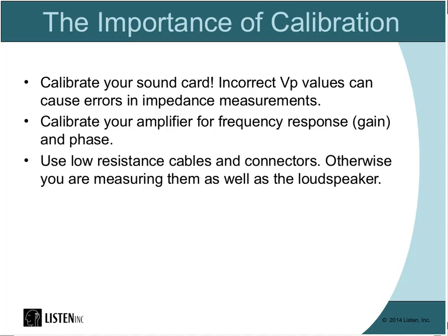And as always, it's very important to use good cables. We want to use low resistance cables and good connections. Otherwise, you end up measuring the loudspeaker and the cables together. And I've seen many cases where people got thin cable running for a very long distance, say into a test chamber, and then the test equipment's on the outside, and it can be even a couple of ohms with the cable, and you end up measuring a 4-ohm loudspeaker. It looks like 6 ohms because of the cable in front of it, the speaker cable.